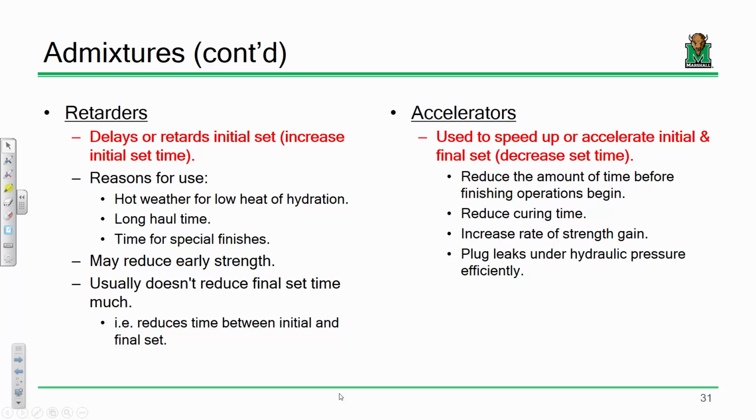Okay, accelerators and retarders. So accelerators do exactly what you would think. They speed up curing. Now you might be thinking to yourself, why in the heck would you want to speed that up? Wouldn't you want more time to work with concrete? Well, it depends on your application. If you've got some hydraulic pressure situation, you've got a leak and you need to plug that leak fast, an accelerator might be an advantageous component. Retarders, now retarders are going to do the exact opposite.